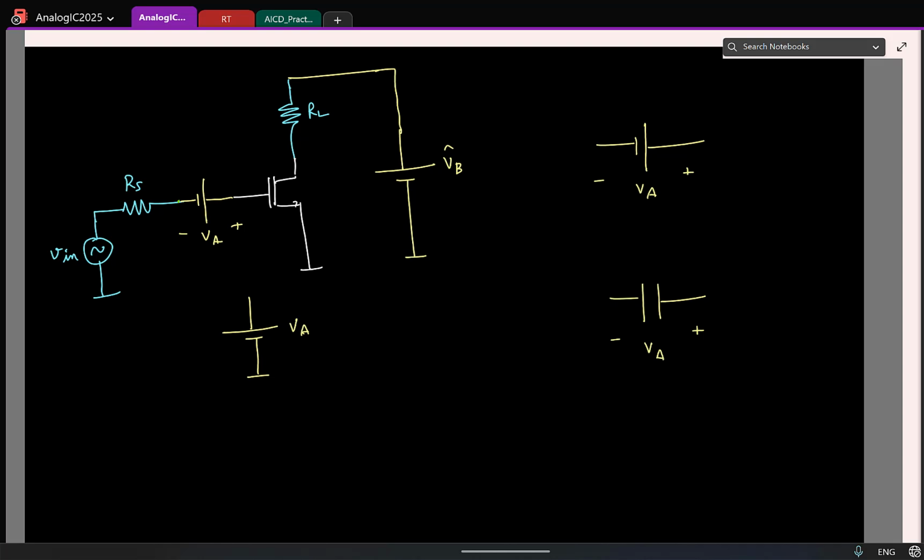I mean, Q is C times V. V is fixed. So if the charge has to be infinity, what should go to infinity? So if the capacitance value ideally tends to infinity, this is the same as having an ideal voltage source. Is that clear? So if let us say C1 tends to infinity, this basically behaves like an ideal voltage source.